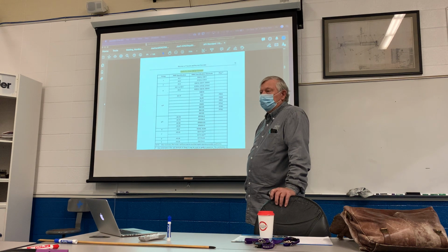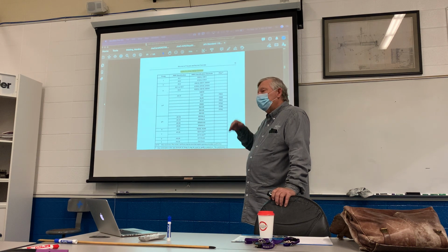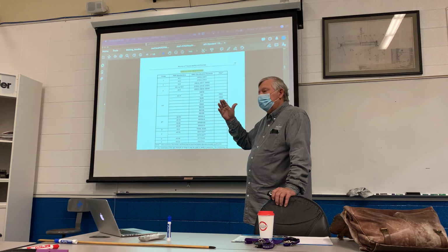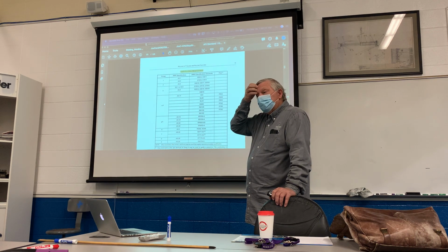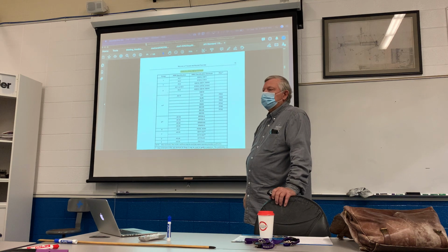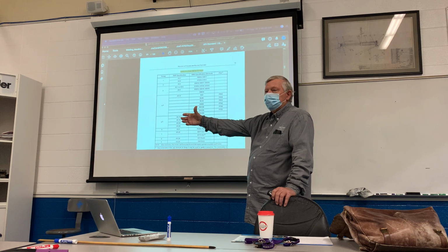Because this particular company is operating under a special permit to operate at abnormally high pressures continuously. They have a special DOT permit to run 1,333 PSI maximum, which is killer stupid high for natural gas. But they have to have it in some places because of the distances between their compressor stations. So by the time it leaves one compressor station at 1,300 PSI, and it travels the 100 miles or 150 miles to the next compressor station, by the time that gas gets to the compressor station, it's down to 800